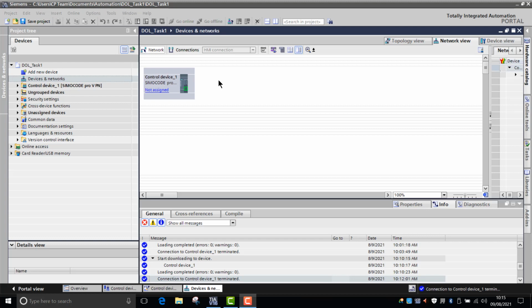So in the majority of applications, the power factor typically fluctuates more than the actual motor current, and that works particularly favorable with the lower end performance range of motors. And for that reason, the monitoring of the power factor comes into consideration to detect faults. An example of a fault that it might detect is the breakage of a drive belt or even a drive shaft.